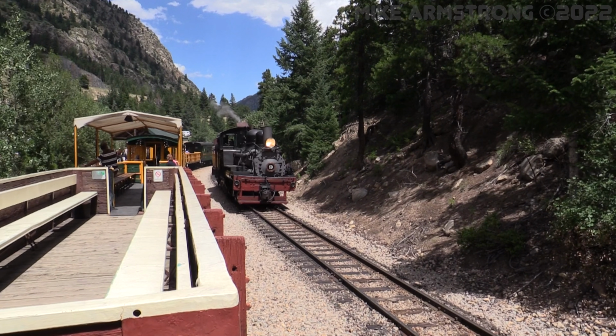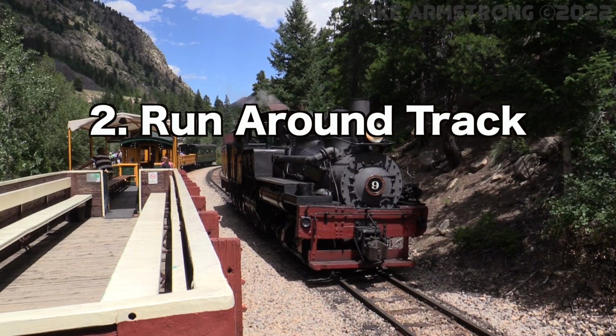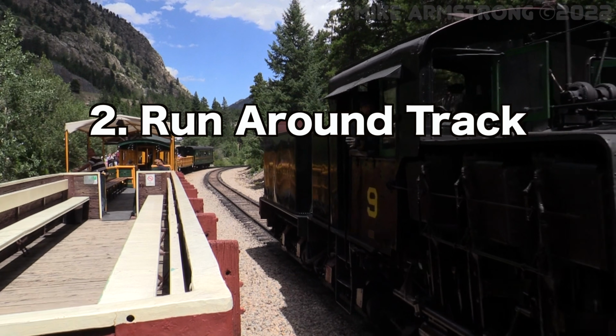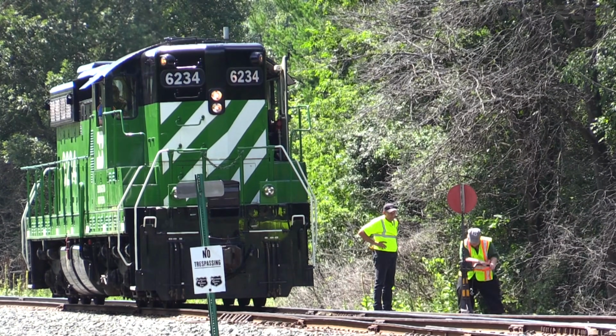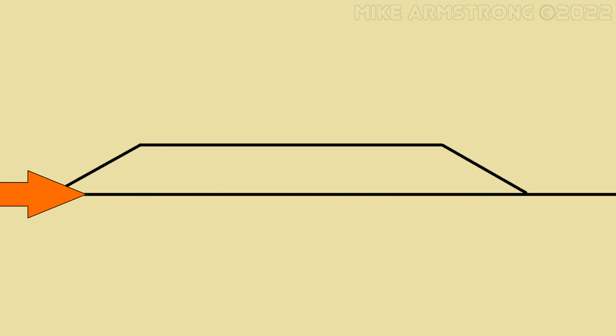A second situation in which a train might need to turn around is if there is a runaround track or passing siding. In this case, there is a short section of parallel running second track. Switches at both ends connect the siding back into the main line. To turn the train around, the crew will pull the train forward and come to a stop either on the main or the siding within the limits of the 2 switches.